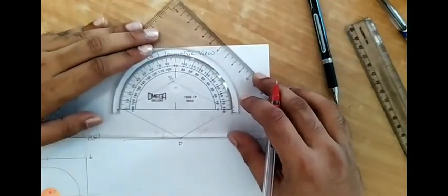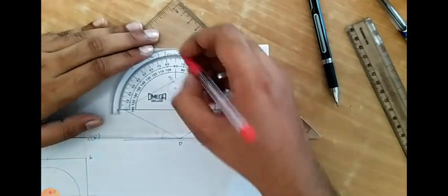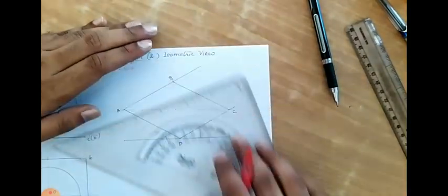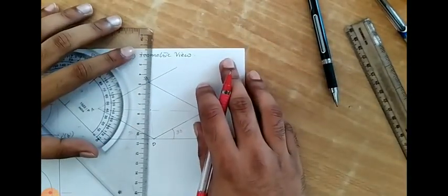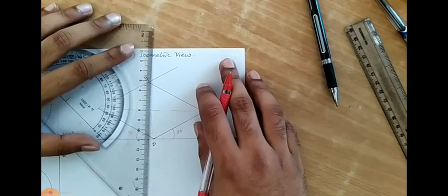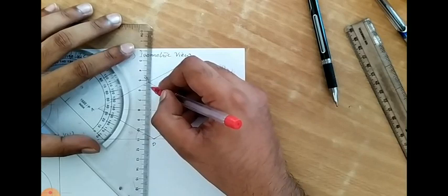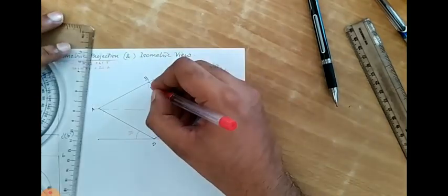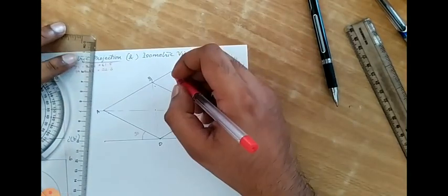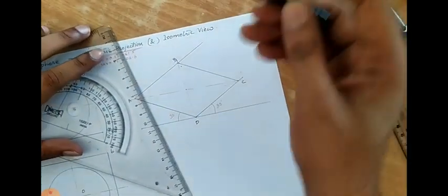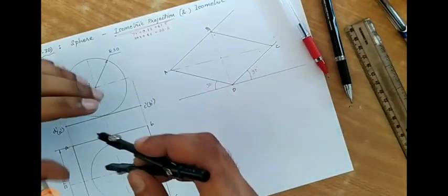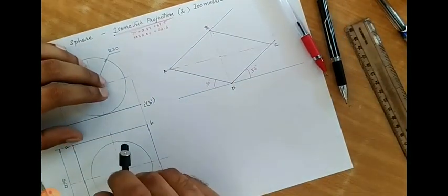So from the center point, the perpendicular distance to the top, I am marking the perpendicular inclination, and the value I am taking is the value of the height of the center of the sphere from the square lamina. To mark the center, we have to take that height. That height is multiplied, that means 30 is multiplied by 0.82, and I have marked the center there.